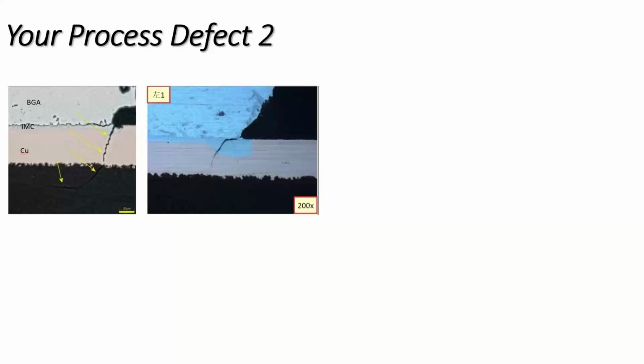Now, thermal expansion and contraction is less likely, I believe, in this particular situation, because these seem to me, from an optical photograph that I've been provided, to be cracks generated mechanically. So I don't necessarily think they're a thermal failure.